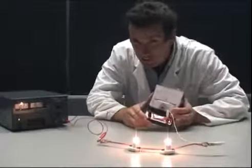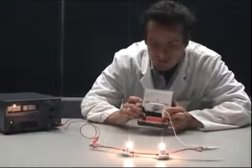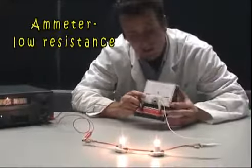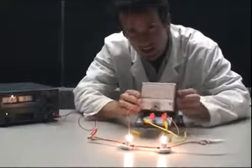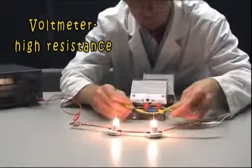We monitor our circuits with voltmeters and ammeters. An ammeter has very low resistance, and it is wired in series with the circuit you're measuring. The current goes right through the ammeter when you make a measurement. A voltmeter, on the other hand, has very high resistance, and it is wired in parallel when you make a measurement.